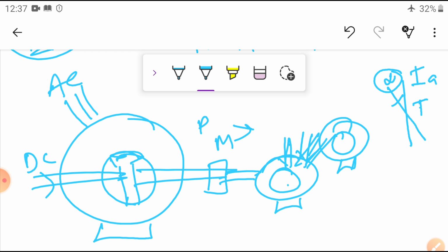This torque is developed in such a way as to meet the extra load on the machine. More torque is developed, so the rotor, which had retarded, will overshoot the axis instead of settling.